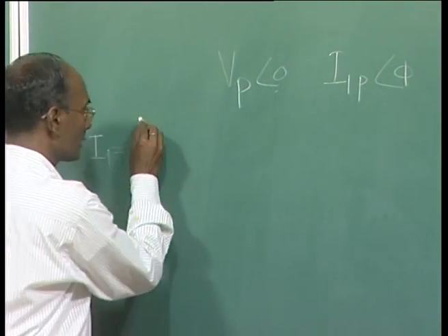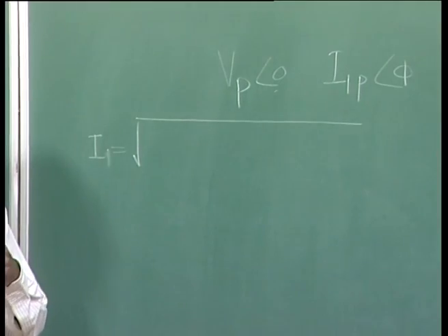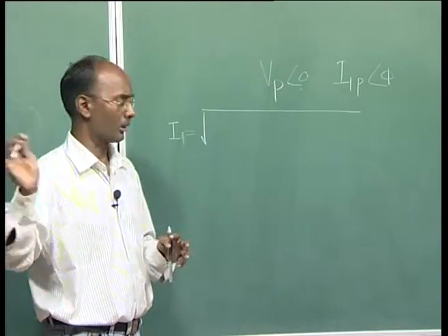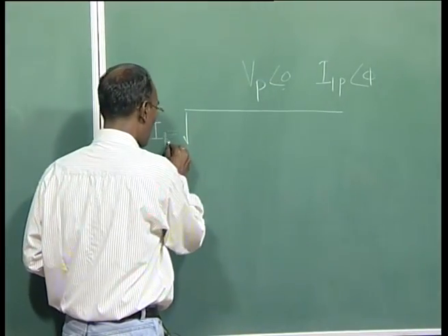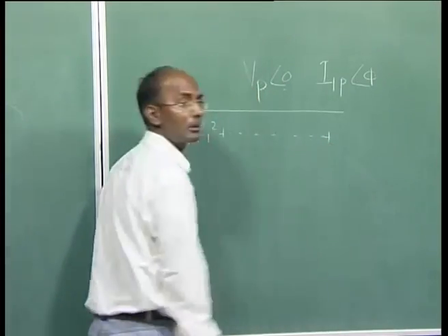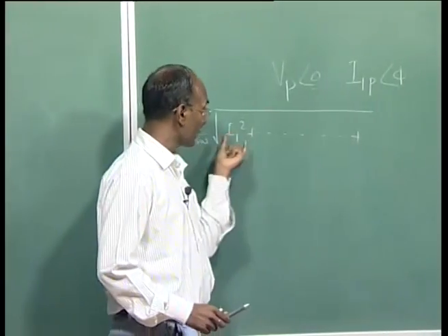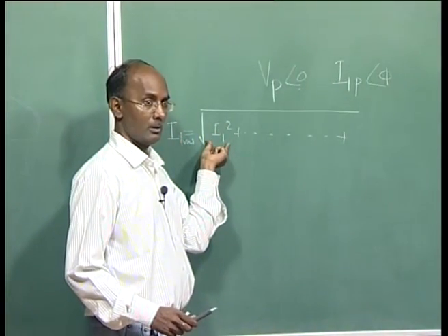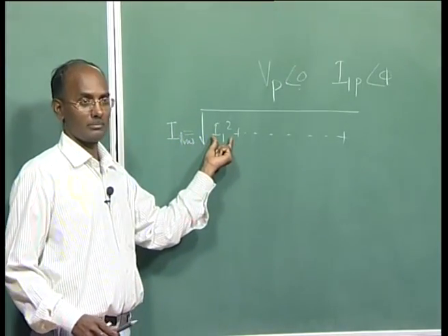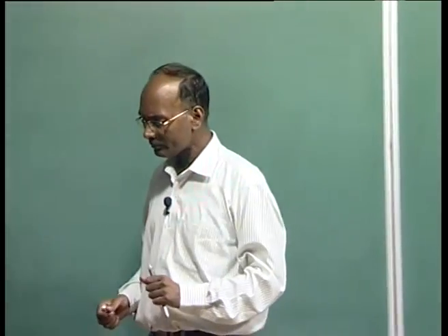This is defined as the total RMS I am talking about, for a current having many harmonics, including fundamental, fifth, third, whatever you can say. So this one is your RMS. It is nothing but I1 squared plus all the other components. But here we are taking only this component. So always this value is larger than this value. It may be equal if the other harmonics are zero.